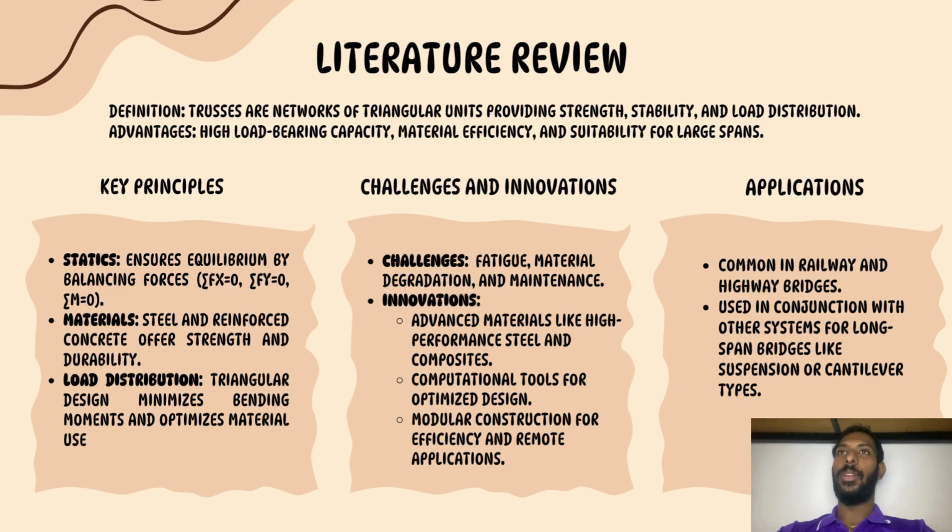Literature review on trusses in bridges. Trusses are networks of triangular units providing strength, stability, and load distribution. Advantages are high load-bearing capacity, material efficiency, and suitability for larger spans. The key principle is statics, which ensures equilibrium by balancing forces: the sum of Fx equals 0, the sum of Fy equals 0, and the sum of M equals 0. Materials: steel and reinforced concrete offer strength and durability. Load distribution: the triangular design minimizes bending moments and optimizes material use.